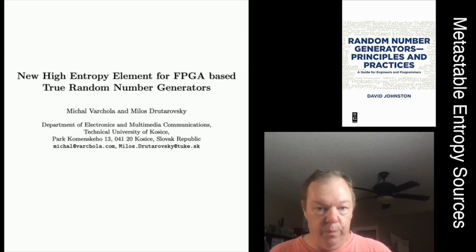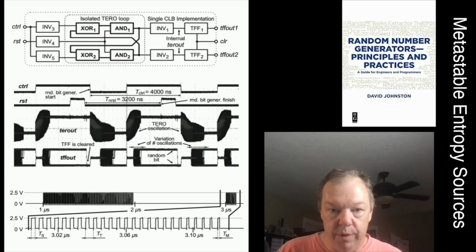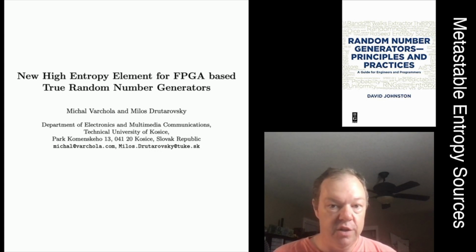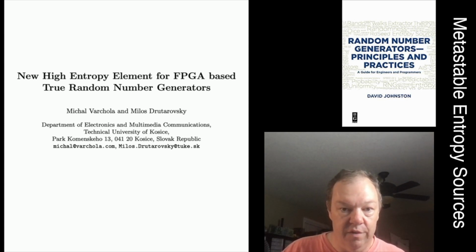Okay, so we're now going to look at one that was designed for FPGAs, so field programmable gate array. This is a chip which has a set of programmable logic elements and programmable interconnects, and you can design digital logic and put it on those chips. They tend to be big and expensive compared to custom silicon because they're programmable, but they're very useful for being able to design circuits which you either don't need a lot of, so you don't want to build custom silicon, or you want to reconfigure.